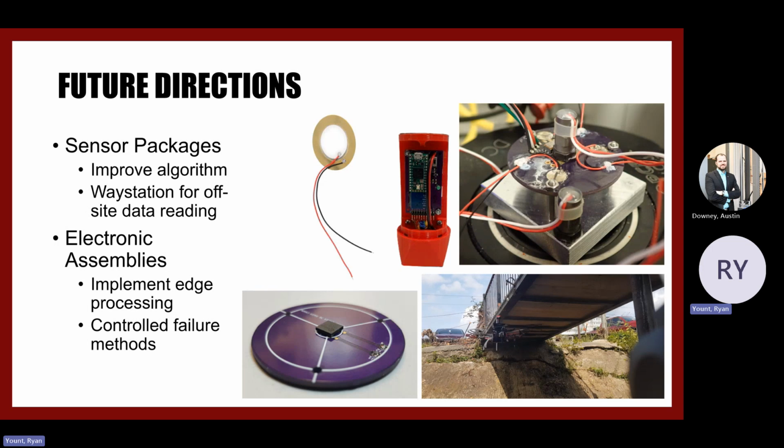Obviously, we just soldered a component on there and tried to get it to fall off. But if you wanted to control this even more, you could look at the exact amount of solder that you were putting to attach each component. And then you could also change the orientation of the component and change the orientation of the PCB and different things like that.